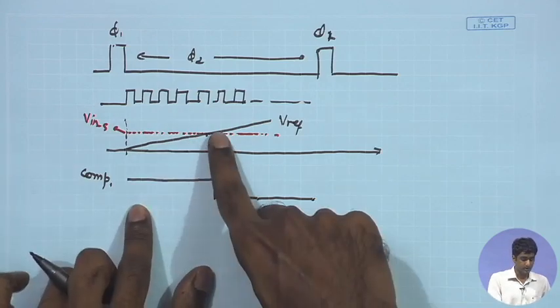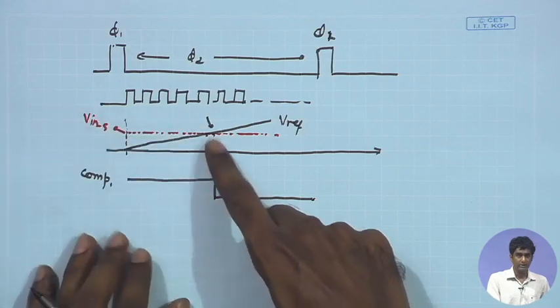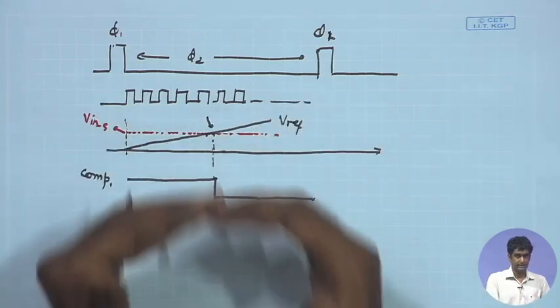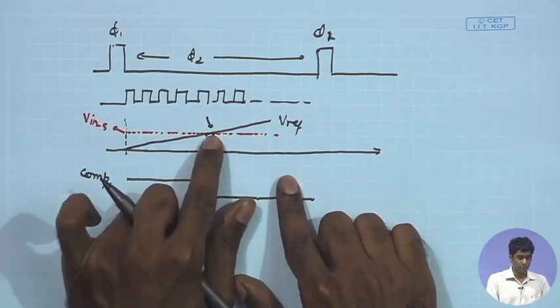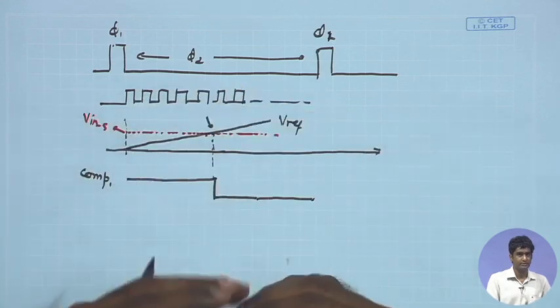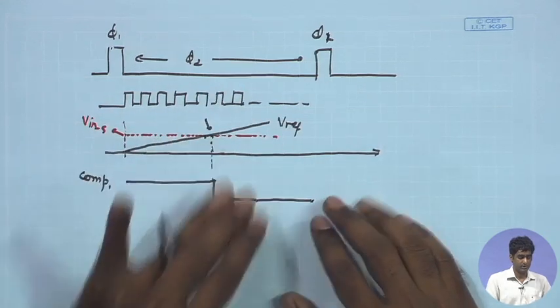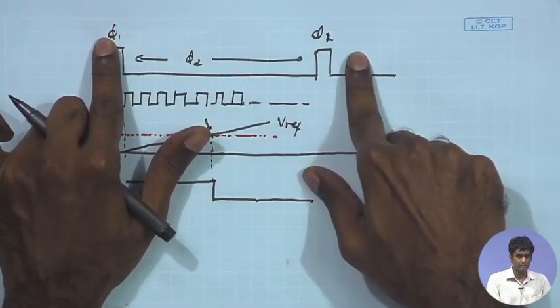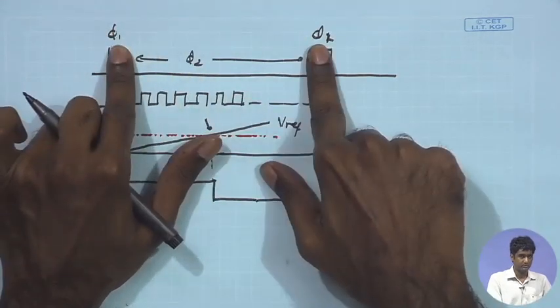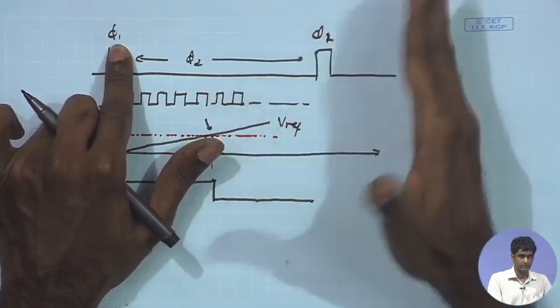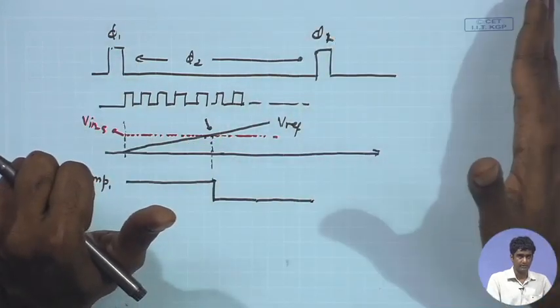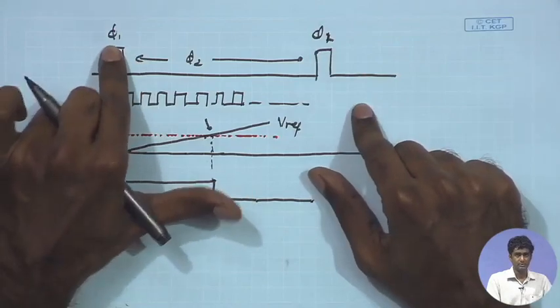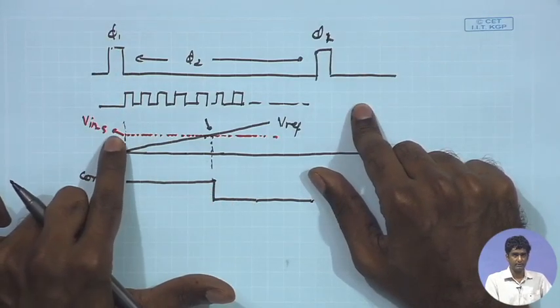where we need to identify the transition point and make sure that whatever counter output is available till this point is transferred to a set of registers and made available as the output digital word for this particular conversion cycle. So, this is one particular conversion cycle. After the phi 1 comes again, the next cycle begins. In this cycle the conversion is happening on the particular sample data that is available over here.